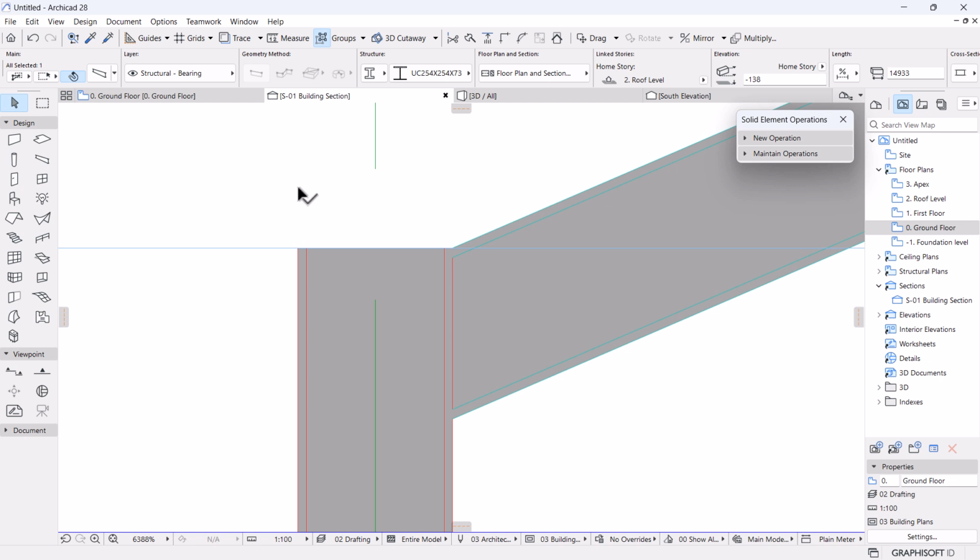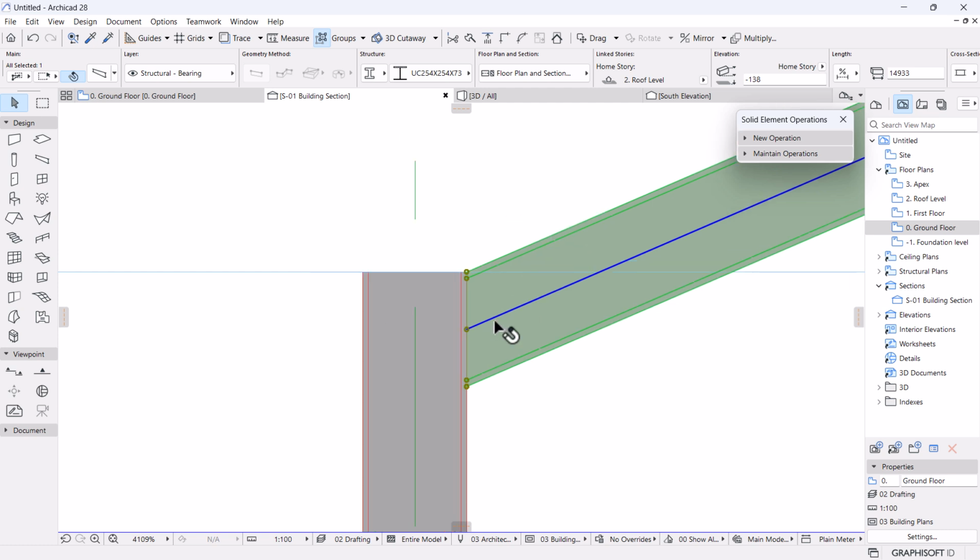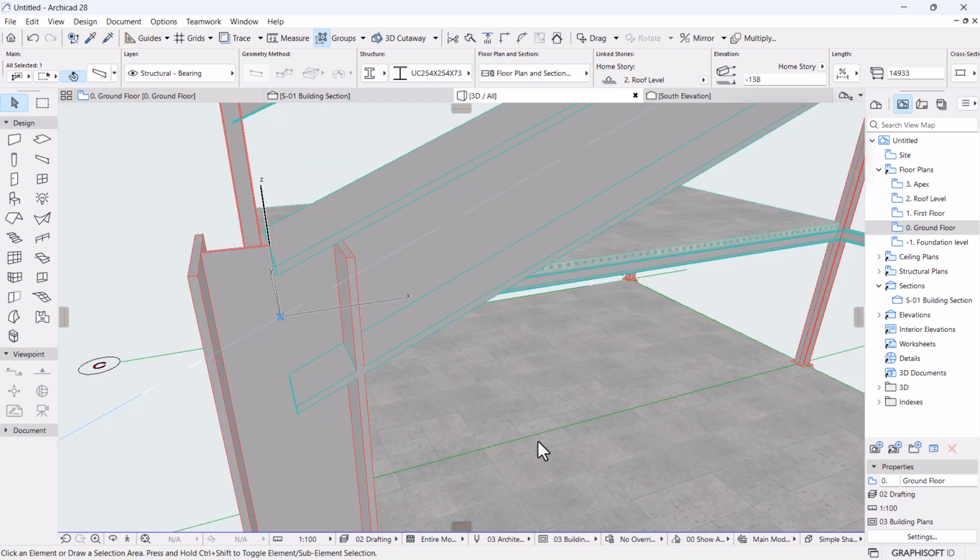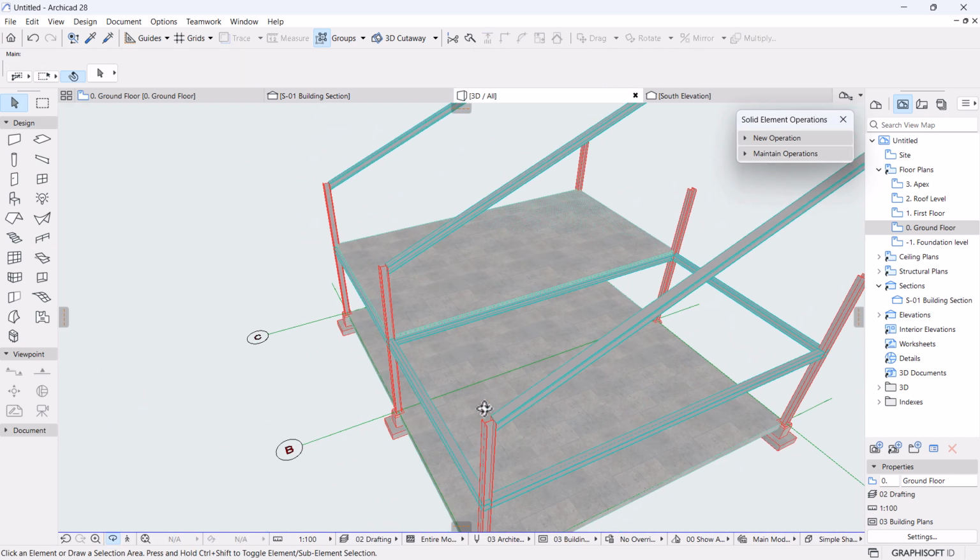But I think in future projects I can avoid this kind of tedious process by making sure of the positioning first before I change the profile or the structure of the column. I should always determine the reference line point within the beam. Okay, so that's basically it.